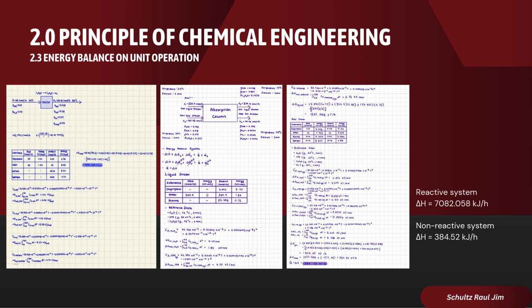To find the changes in enthalpy for the component, we use the specific heat capacity at constant pressure, Cp, of the components to be inserted in the change in enthalpy equation due to change in temperature. After calculating all the values, we would get the enthalpy change of liquid stream as 1257.1688 kJ per hour.